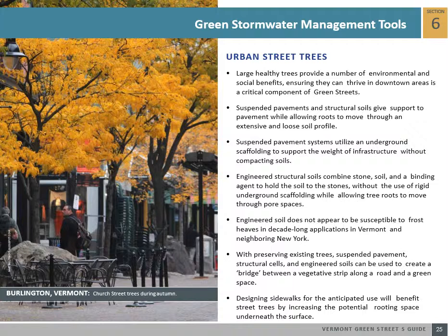Common constraints with urban street trees include: trees require regular, skilled maintenance to ensure long-term growth and health. Trees contribute leaf fall to street surfaces, increasing need for regular street sweeping efforts. Species selection is limited by above-ground infrastructure and utilities, making larger varieties ill-suited where overhanging power lines may conflict.